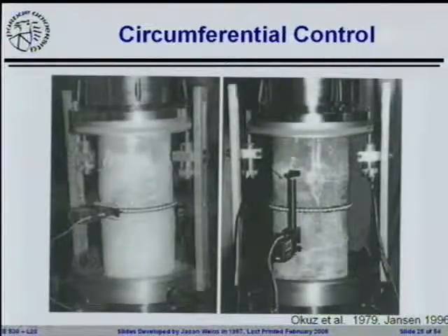And while this is not necessarily a problem, as the strength of a material goes up, the material typically becomes more brittle. We saw this last class where we said the pre-peak response becomes more linear, the post-peak response drops off more rapidly, and the material starts to become incredibly brittle. What people were trying to do is ask, how do we capture the overall stress-strain response of these really, really brittle materials? Instead of using the old school method where they're putting concrete inside of a steel cylinder, or this case where you actually measure the length, because you can get into some problems just measuring the length when you get to really stiff materials, they said, are there alternatives?